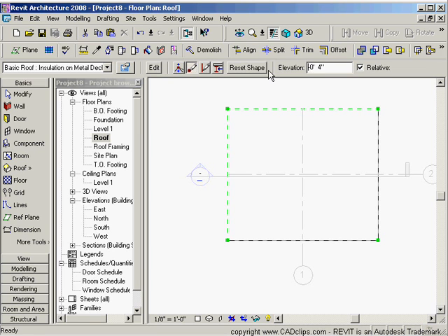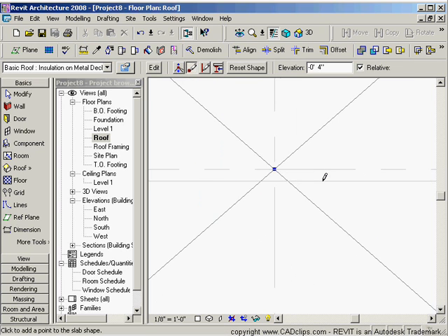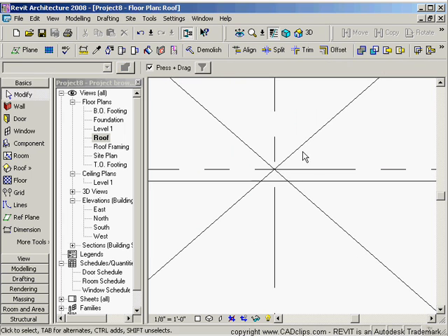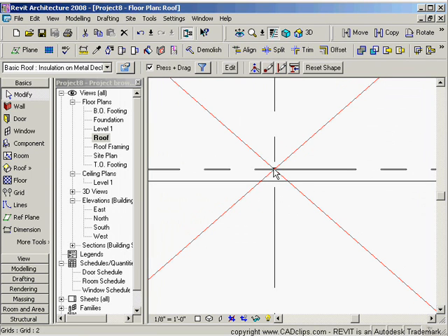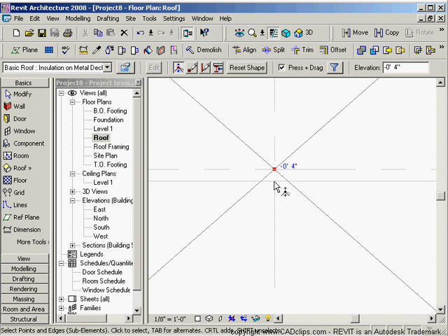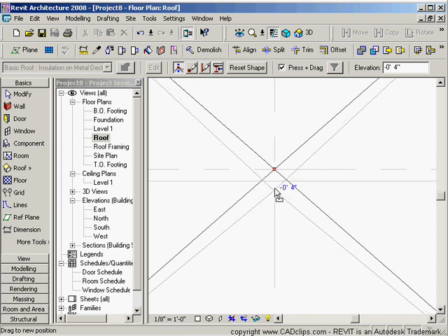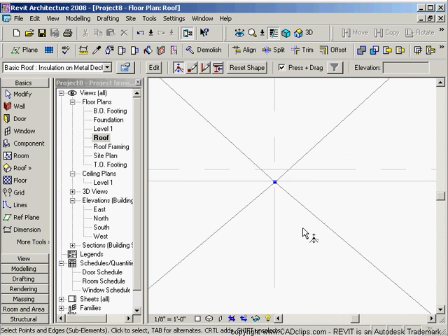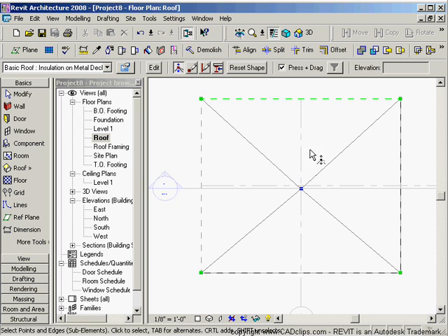Okay, and I'm just going to go down, zoom in, and I'm trying to zoom, it's not zooming, and I'm going to pick. Now it let me zoom, escape. I'm going to pick on here, I'm going to tab, grab that point, maybe move it over a bit. Okay, it doesn't matter. Oh, I need to use my edit option there to grab that and drag that point there. Okay, so that is now sloping down. Click out, escape. There's my sloping slab.